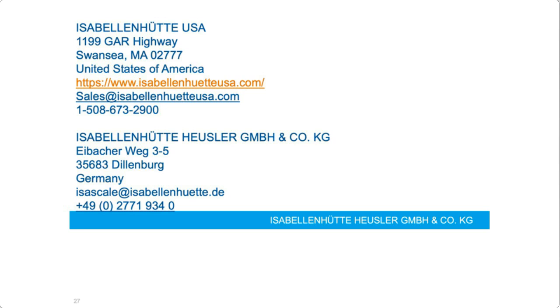Yeah, that is a good question too. Thank you. So we currently have B samples available of our IVT 3.0 Pro product. And again, as a reminder, the Pro version includes the isolation monitoring functionality and the voltage sensing functionality, and has the full ASIL ratings on all these functions. And so B samples, what does that mean? These are functional prototypes that haven't gone through validation yet. So this validation still needs to be done.